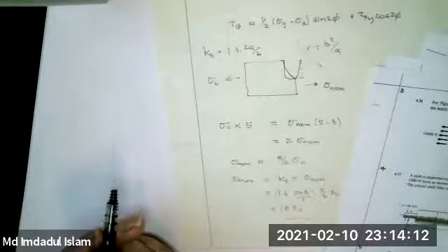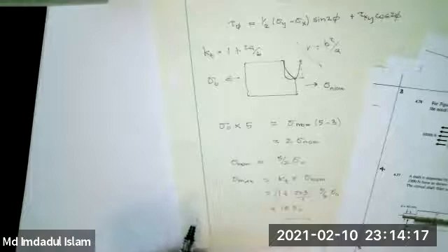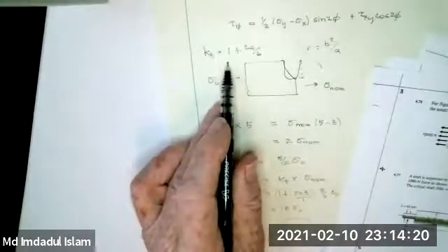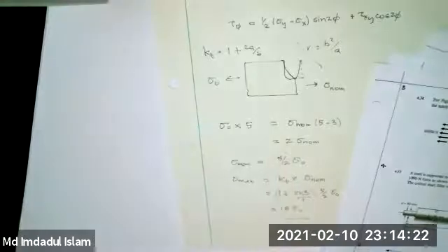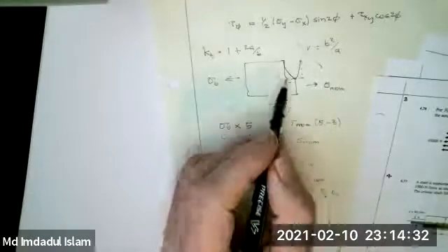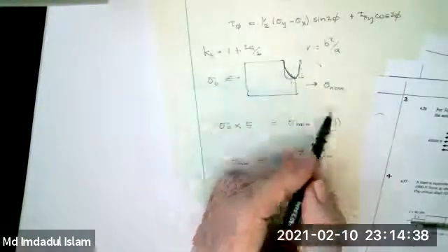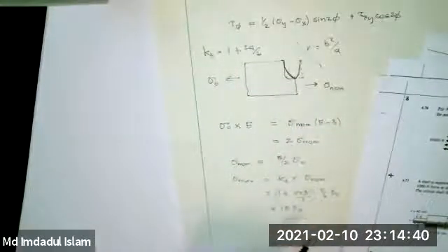If you're given the local root radius, or you wanted to take this here, I think when you're doing this, I can see what you're thinking. You could perhaps take the R here as being 1 inch. Can you see what you're pointing to? And you see which one's bigger. Okay, I'm pretty sure the one I did is bigger because it's got a smaller radius. I put in an ellipse. That's going to have a smaller radius than this radius here, and so that'll be a bigger KT. So you want to try and be conservative, so you want to pick the bigger value.